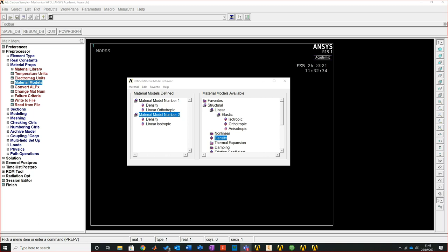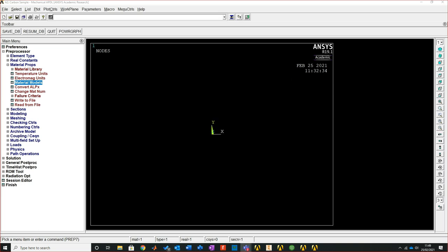It's always been interesting trying to learn from Tony about the best laying up procedures and things like that. The important things about laying up are the orientation of the carbon, how it's been set up, where it's actually sitting, how the interface is there. That's why I focus on that first. Introduce the geometry, and then it will just be what I tell it to be. So I'll close that, because that now is my materials model set up.